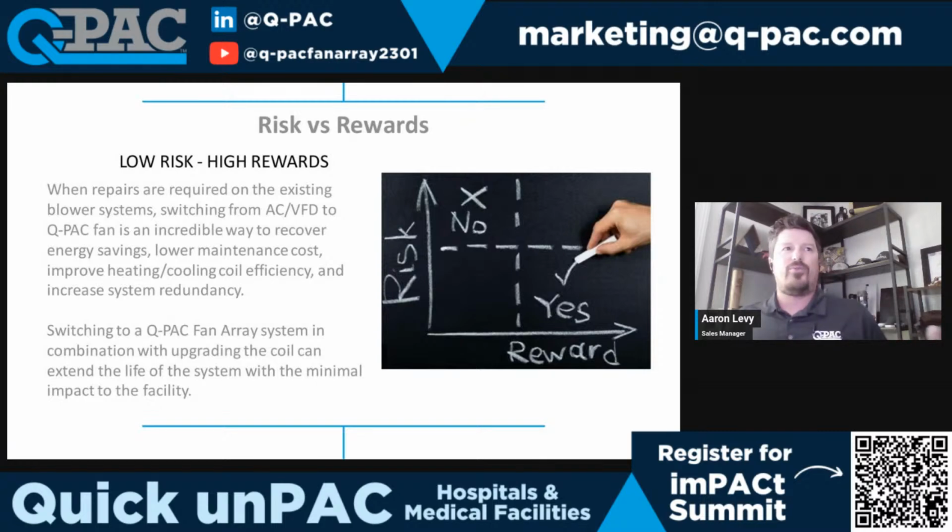And that's where, even switching from just the air side, looking at a cabinet that's still in really good condition, replacing a coil and a fan system together can extend the life of that system another 5 to 10 years. So it becomes like a third of the cost of having to replace a system, especially when you take into account some of the engineering costs it would take to get some of that old equipment out of the building, given the location it may be in.